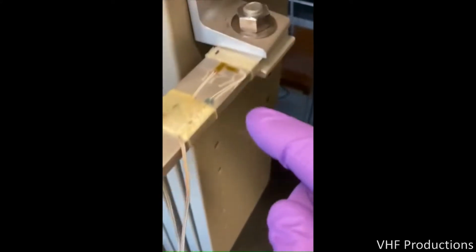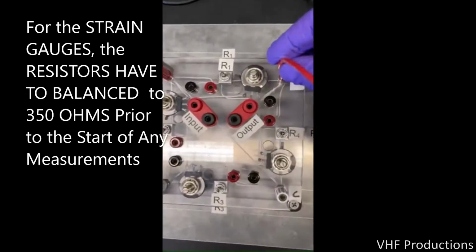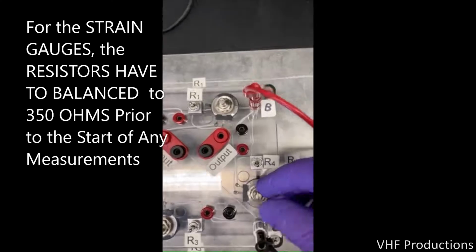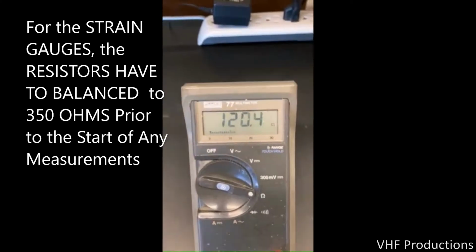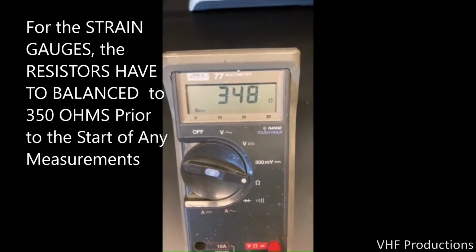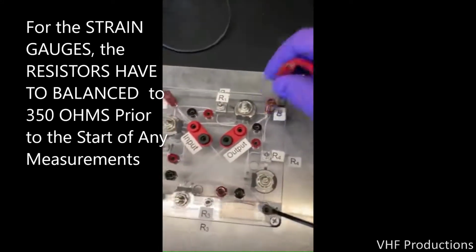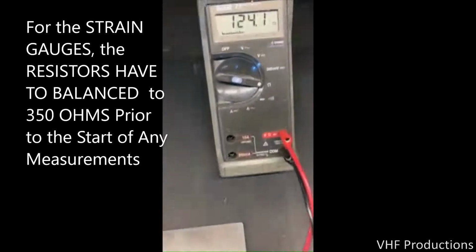We repeat this process for each of the other three legs or three sides of the Wheatstone Bridge. Once we've set each potentiometer to exactly 350 ohms, then we can switch any side of the bridge to use either the resistor or switch it to a strain gauge plugged into the strain gauge input pins on that side of the bridge. And then we can select the strain gauge as the input simply by flipping the switch to that input side.